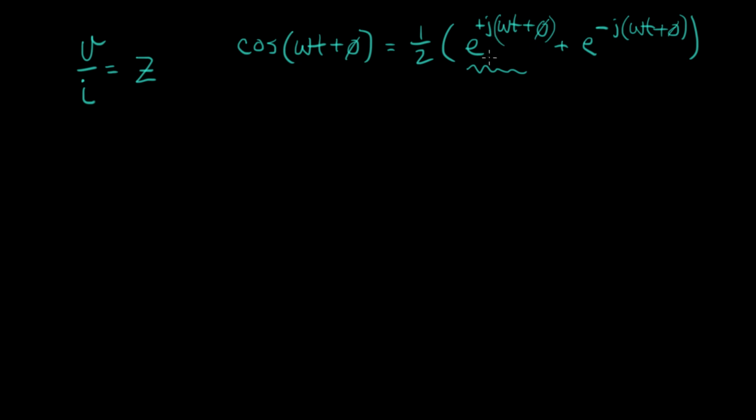And so when we made up the concept of impedance, we assumed that V or I was of this form, this complex exponential. When we put that through our components, we came up with the idea of impedance. As a review, the impedance of a resistor turned out to be just R. That's the ratio of V to I in a resistor.